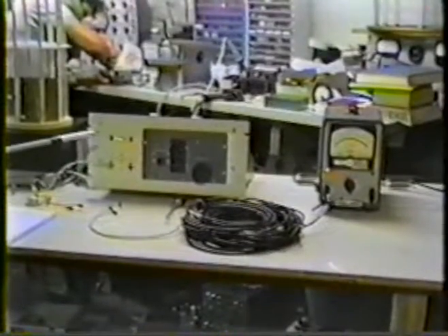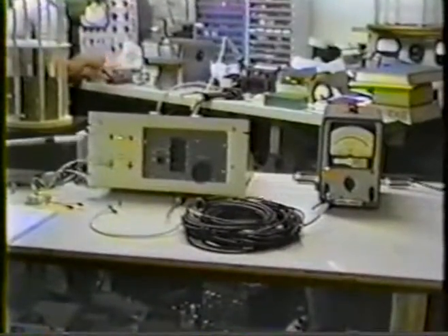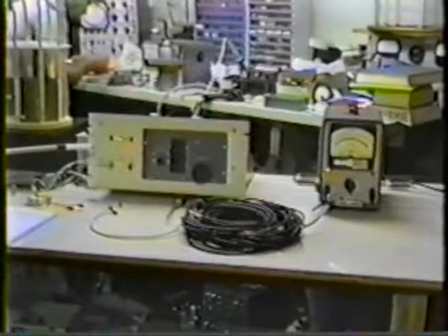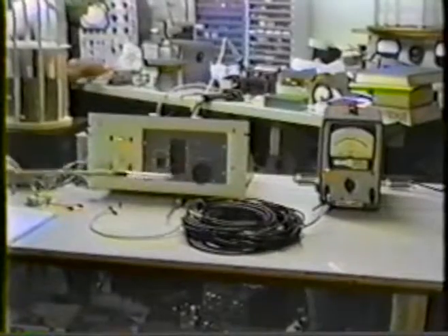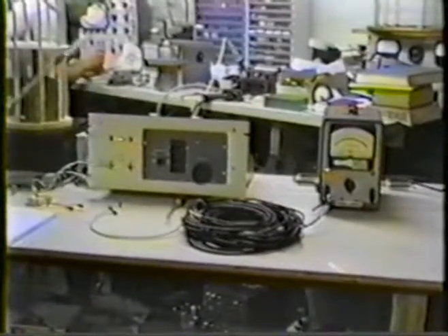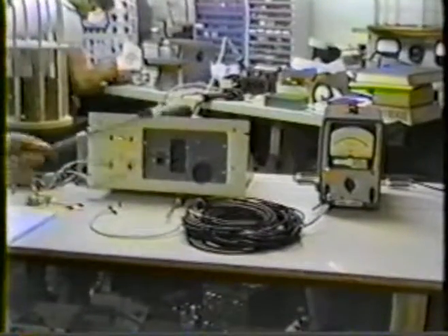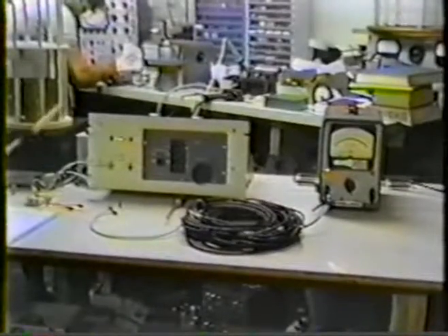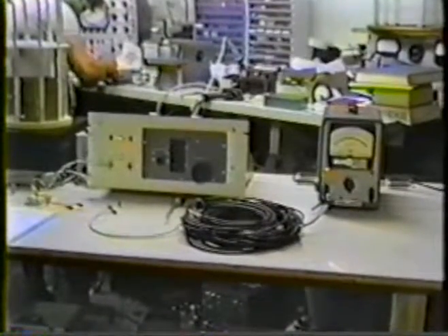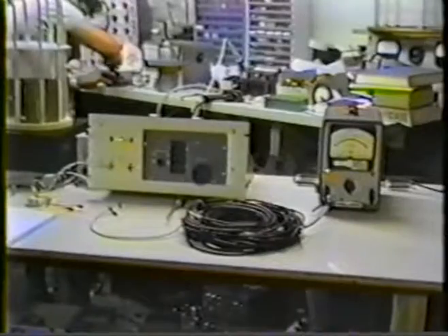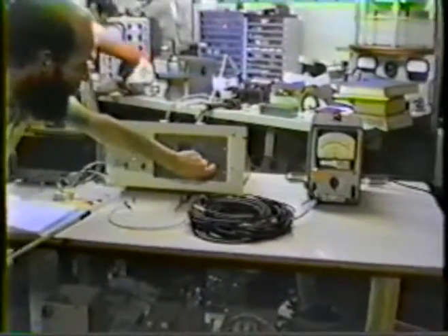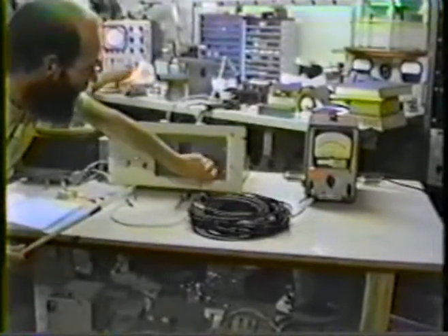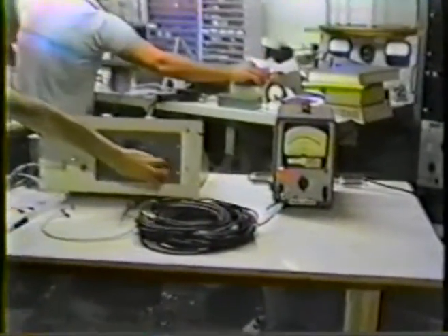The oscillator has gone through another 180 degrees of shift and is producing a right side up impulse to match the reflected, now right side up, impulse. And this process keeps on going on and on until the voltage rises to a level where the losses of the system prevent any further increase. So what we're going to do is sweep the frequency here and find the resonance point of this cable to determine propagating velocity.